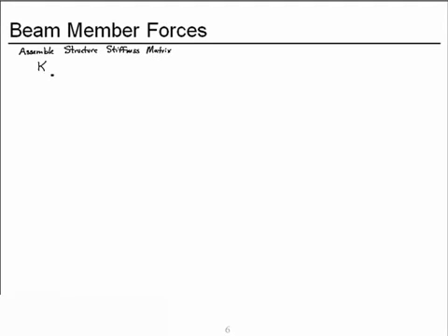And the structure stiffness matrix is given by capital K, and it'll be the sum of little k1 and little k2. But I want to point out it's not just a 4x4 matrix. This summation is by degree of freedom. So capital K will be a 6x6 matrix.